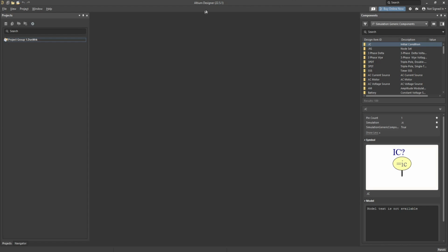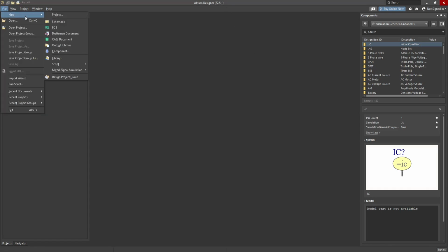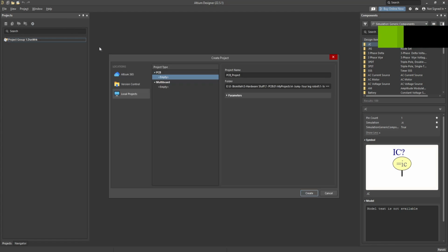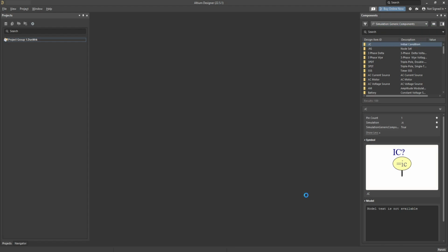In this video, we will be learning how to design a PCB using Altium Designer. So this is the default screen. When you open the Altium Designer, the first thing you need to do is to go to the new project and save the project with some specific name. I call it test 01, create,